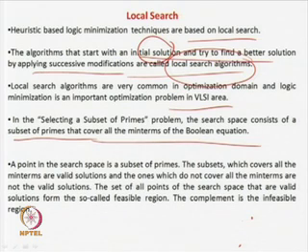But if you take the previous lecture, where we were given some prime implicants which cover a function, how can you go for a local search in this? You randomly take a subset of prime implicants which cover the function, then you tweak something: you remove one prime implicant and put another, or you remove a subset of the prime implicants from the set and add another subset which will still cover the function.